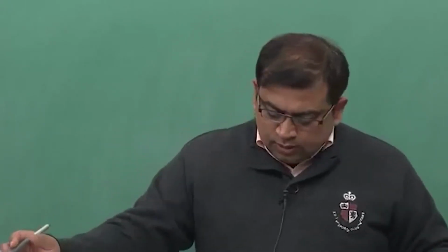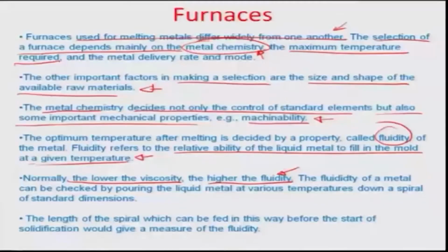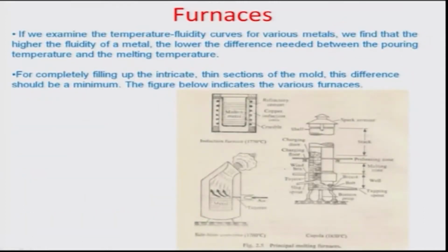Okay. So, the fluidity always is checked before doing a casting or pouring into a casting, so that you can see whether the output material that you are having out of the furnace is of the correct fluidity, or the correct level of requirements imposed by the molds.